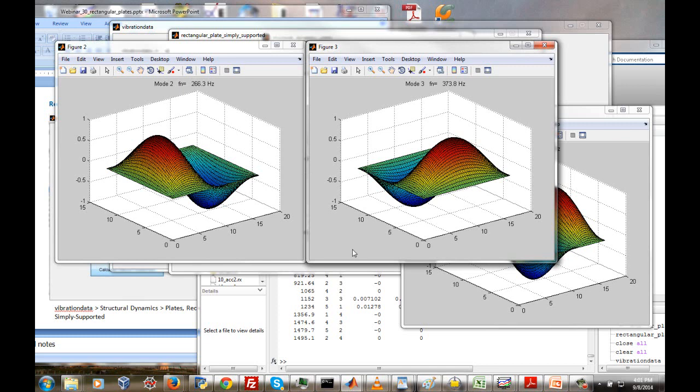In other words, the participation factor of each of those 2 modes is 0. If we had some reason to excite those and we were applying a base excitation or enforced motion, we would have to have a differing phase angle, or we would have to have a differing amplitude or both along the perimeter. But for a uniform constant amplitude in phase base input along the perimeter, neither of those 2 modes can be excited.